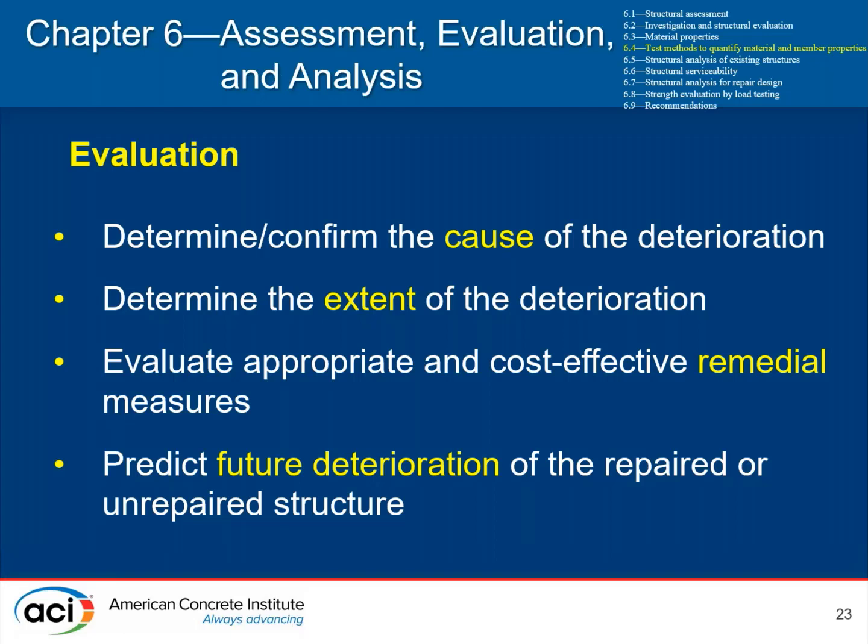So it's important to determine and confirm the cause of deterioration so that adequate repairs can be conducted. It's also then important to determine the extent of deterioration, and you can do that through a variety of techniques, non-destructive techniques, as well as visual techniques and destructive sampling. From there, you evaluate the appropriate and cost-effective remedial measures.